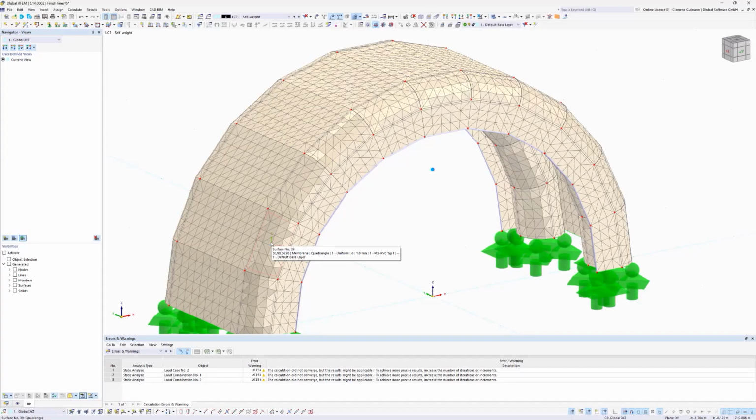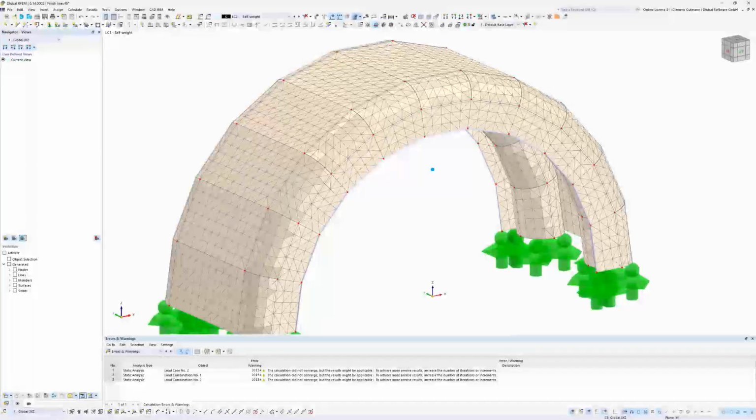And normally, like in the physical world, you would have some contact between the tube and this stretched membrane, and some friction. And while it is quite easy to understand how it works in reality, it's quite difficult to model this using a finite element software, because contact is a highly nonlinear topic, and then also the friction is complicated by itself. Then you have the nonlinearity of the material. So it can be done, but again, the most difficult issue is the high deformations.